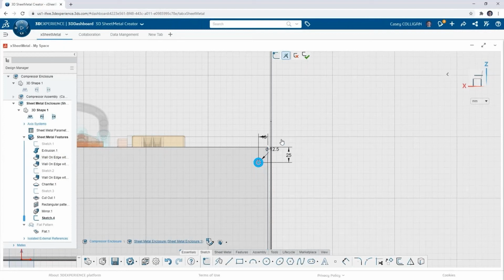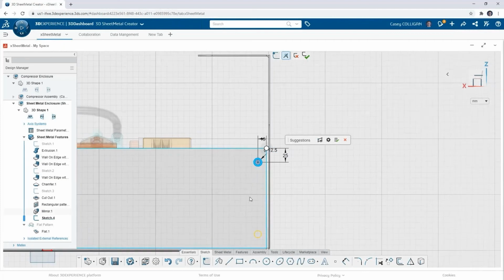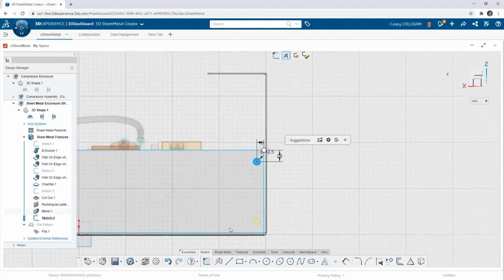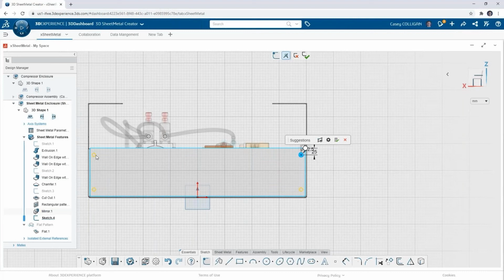So when I click on this button here, we'll see it actually calculated, or assumes, based on where I placed that hole in my geometry, that I want to place 4 other holes in very specific positions, which in this case is exactly where I wanted to put all those other holes. We do get some visibility that shows us basically where the robot references an axis for that positioning. Then we get some options like symmetry. So in this case, the 2 on the left were calculated by symmetry. But watch what happens when I say okay. It actually just created those 3 other sketches for me.